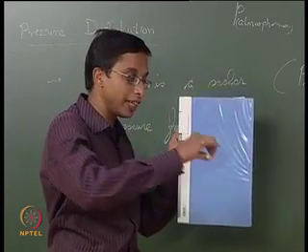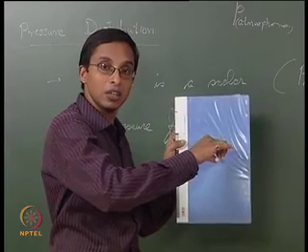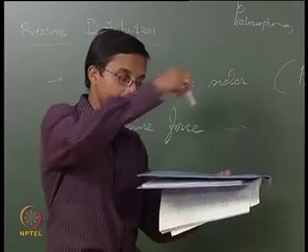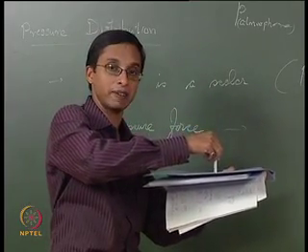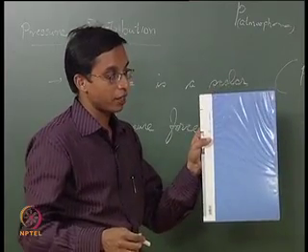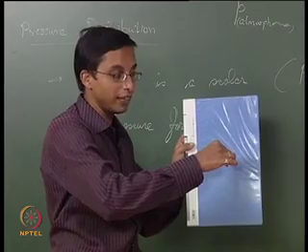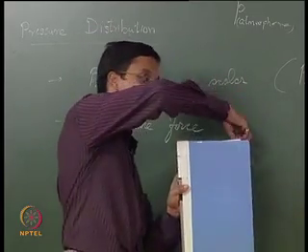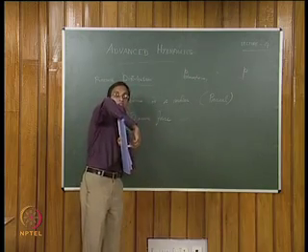Here the force will now be in the horizontal direction. When the plane was horizontal, your force due to pressure was vertically downwards. When it is a vertical plane, your force due to pressure is horizontal and into the plane. Similarly, force can act from the back side into the plane as well.